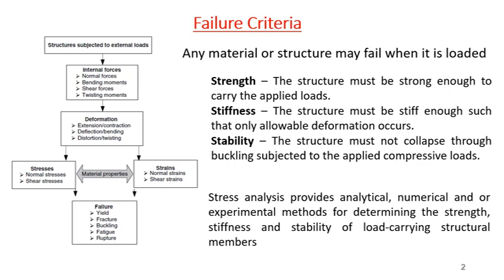Okay, so for example, why we are doing this: we have a structure, a machine member, subjected to external load, and that will cause internal forces, and we find the intensity of those internal forces. So an internal force can be a normal force, tensile or compressive, it can cause a bending moment, right? It can cause shear force due to transverse load, or it causes a twisting moment, or we call it torque. And we know how to find the stresses for those conditions.